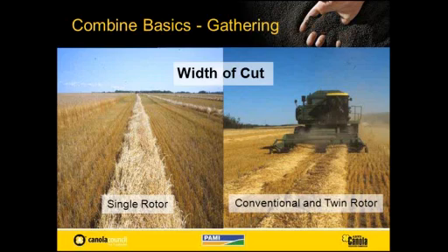And therefore, if you can tolerate going a little higher ground speed with a little narrower windrow, you're going to get better performance, because as you start feeding more and more material, and if you get slugging going into the machine, that's going to cost you a lot of issues in terms of not only loss, but lost time if you're starting to slug the feeder house and plug and things like that.